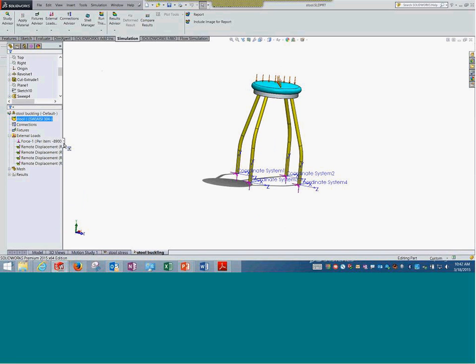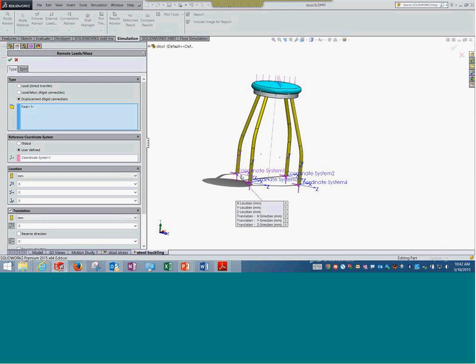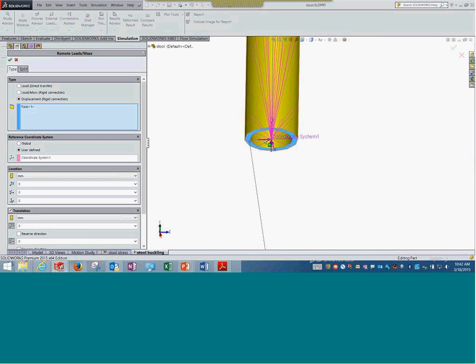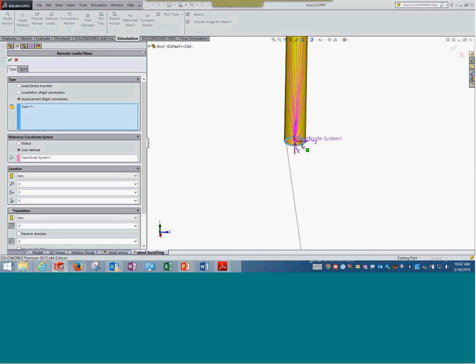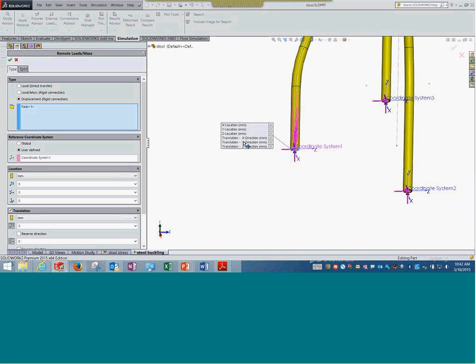Okay. So over here, the interesting fact is about the way this stool is held at the restraint. This is an interesting thing which you want to understand and imbibe. We mount this stool at this surface, and we can use a fixed condition. But definitely that is not the case in the case of a stool. The way it's going to be when it is placed on the floor, it needs to come up. There are different ways in which it could be simulated. One could be a virtual wall as well, or we just apply it and keep it on the floor with some planar displacements being restrained.